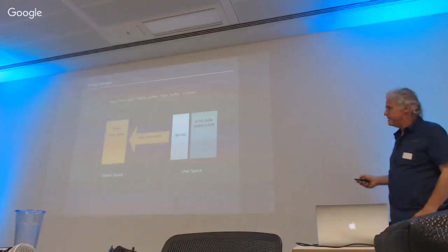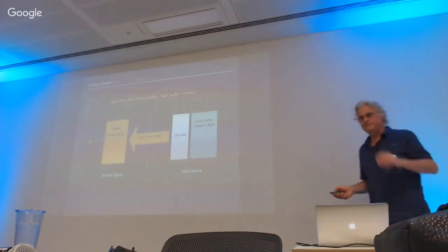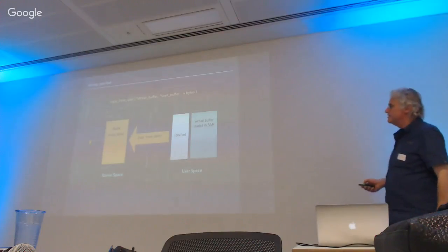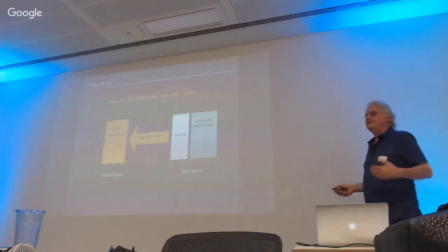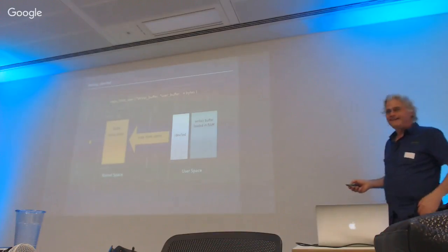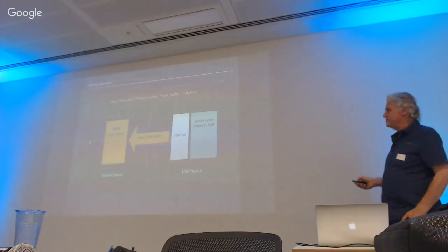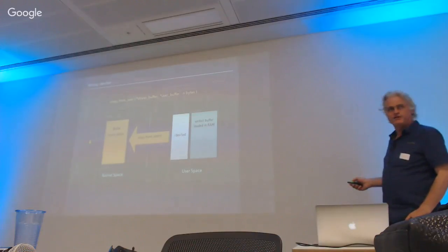And then we can suck the data from there, put it into the driver, and turn the LED on. This is a very neat function. It basically sleeps there until this buffer becomes available in RAM with data from the application.